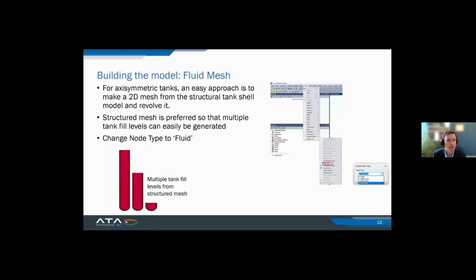The advantage of having a nice structured mesh is that a lot of times when you do these meshes, people ask you for various fill levels. Maybe you want to do your whole CLA or other loads computations in, like, 5-second increments. So you need a whole set of fill levels, and those will all be individual meshes. But by having a nice structured mesh, you can very easily just cut off a few elements, make a new mesh, cut off a few elements, save as a new mesh. The only thing you have to do within the mesh generation is change the fluid type.